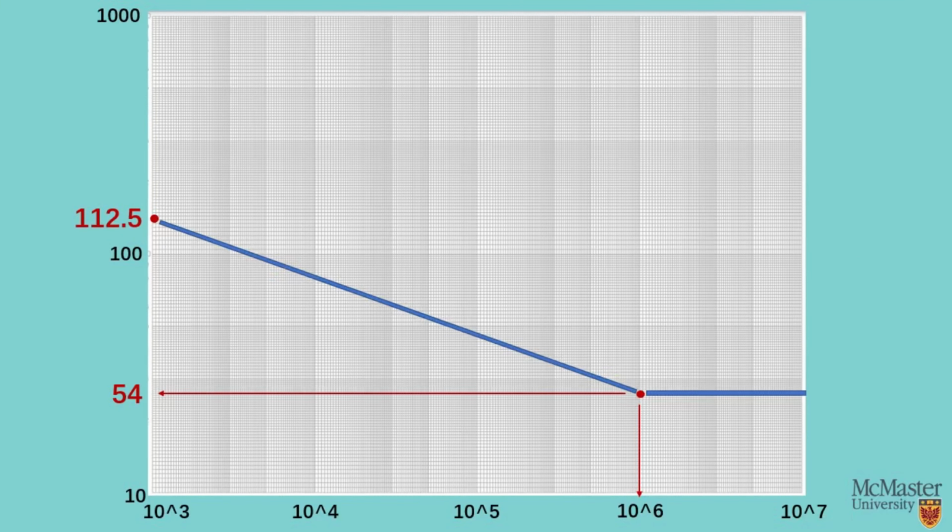Okay, so here's the time to draw the SN curve. The SN curve is drawn by points and lines. So as we can see in this image, the main points, 112.5 and 55, are put at the cycles 10^3 and 10^6 respectively. Just use the points and then connect them. Finish.